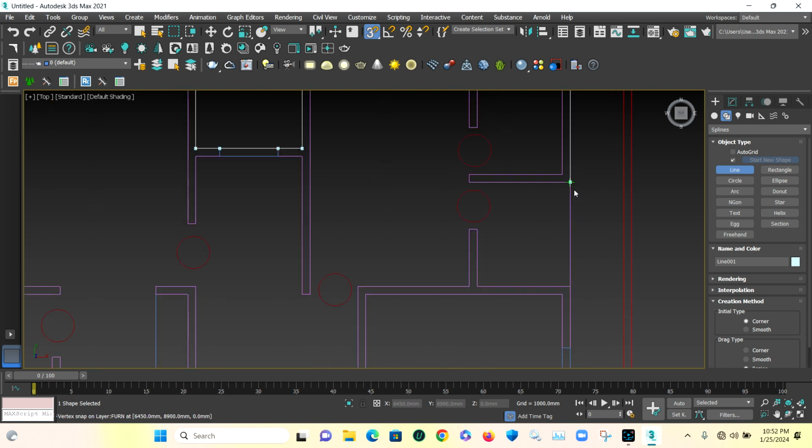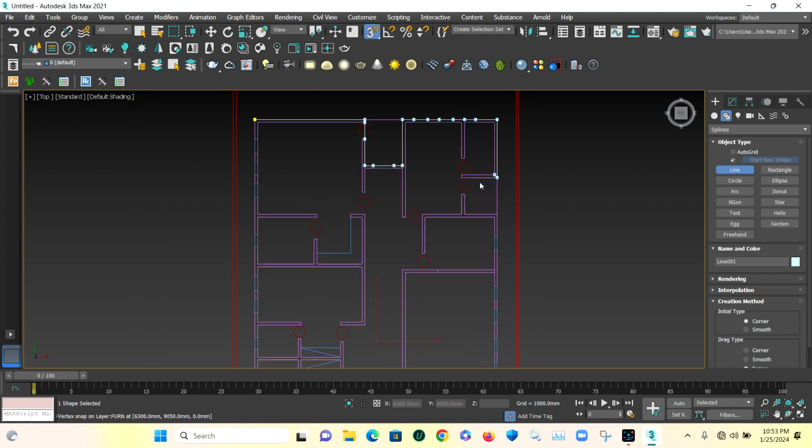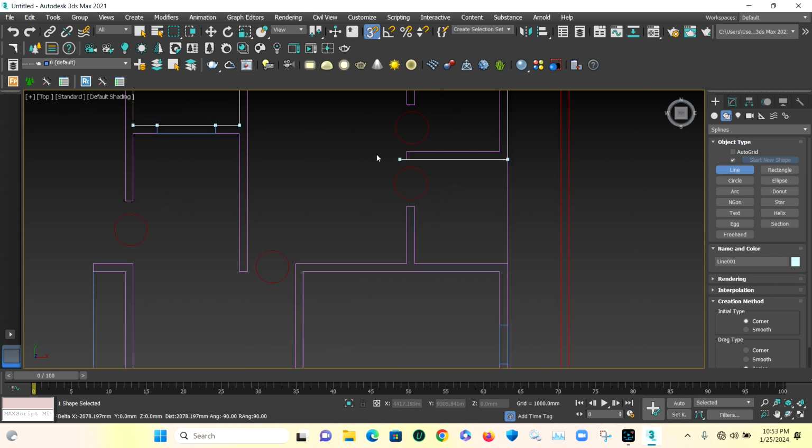Then we'll come in again. If you check, you see that this too is the external part of this drawing. It's a kind of terrace. If you open this door, you come out here. There's no wall here, so it's an external part. Now go in. Then when you go in here, you can see that we don't need to go in, because we're already inside. We want to stop here, that is the line from here to here. So how do you do that? Once you are holding your shift, you just go down and snap here. It will select there.